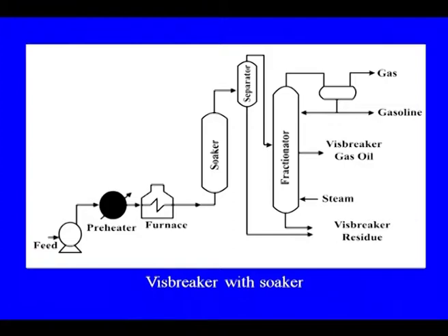From the separator, again as I told you, we get the visbreaker residue, some middle distillates, gas and gasoline, and steam that you add here.